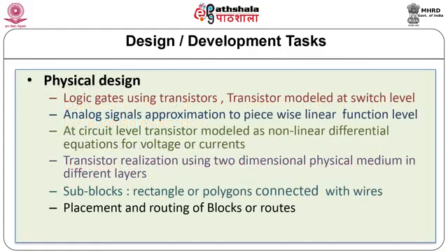Physical design. Logic gates are constructed using transistors. Designing at transistor level demands a different level of dependence on the requirements. Transistors can be modeled at the switch level as bidirectional switches. At the timing level, signals are considered with piecewise linear functions. At circuit level, transistors are modeled using nonlinear differential equations for currents and voltages.